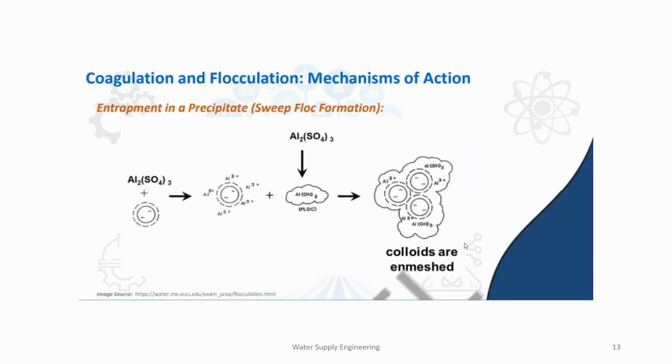Now the last mechanism of action is entrapment in a precipitate, or sweep floc formation. So this is when we are adding a larger amount of coagulant into the water to be treated. Then that coagulant will precipitate out, entrapping the colloids on the way it settles down.